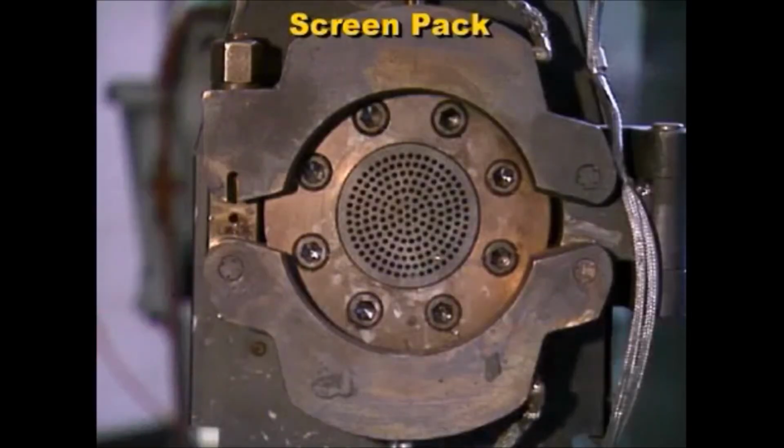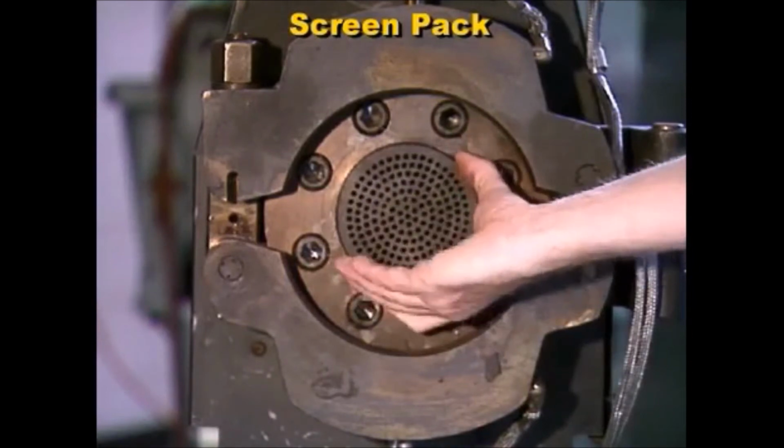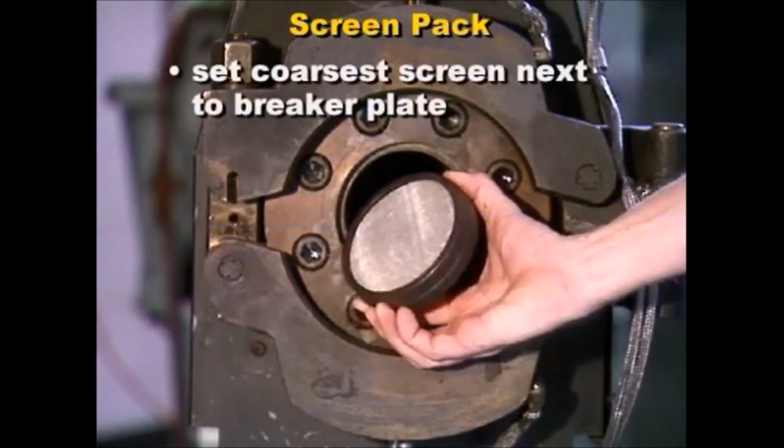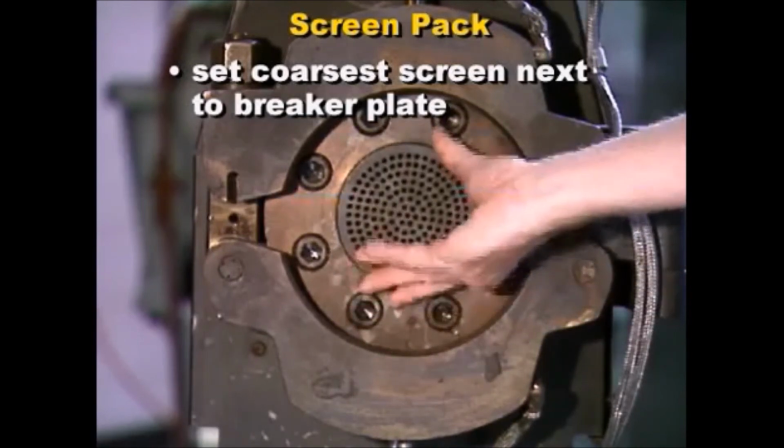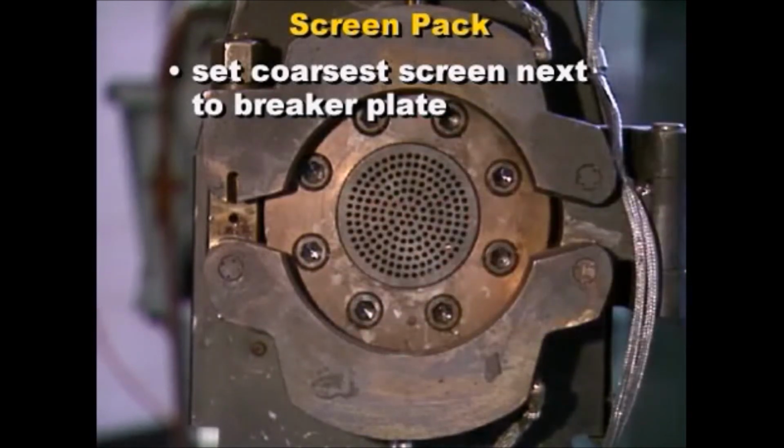The screen pack must be set in place with the coarsest screen next to the breaker plate, so each screen can support a finer one. Otherwise, the pressure difference may break the fine wires, contaminating the product and possibly doing permanent damage to the die.